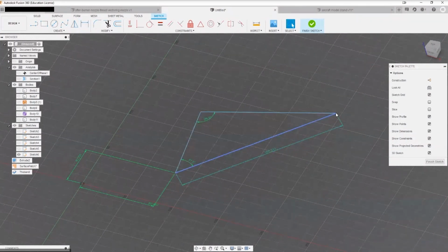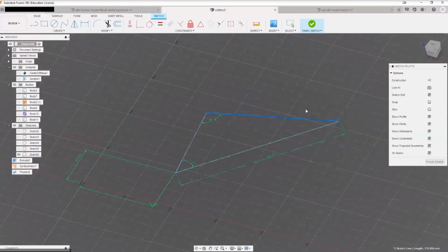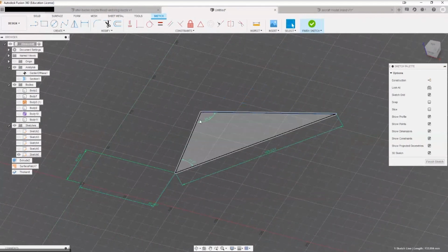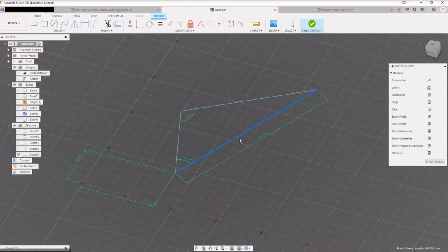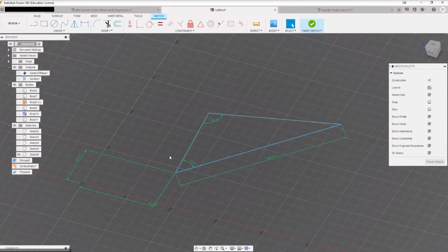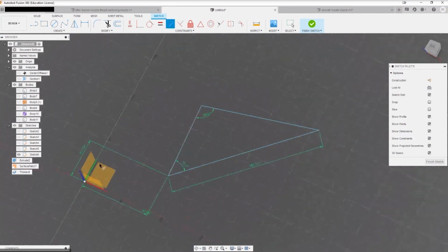Yeah. So let's see what happens now. Oh, suddenly this is rotating, right? So we've fixed the point, we've fixed the angles between them, fixed the distance, but you need to sort that out. Again, when you're designing something, you're going to have a specified set of requirements, so you'll already have all of these dimensions ready. We can switch on the origin, because apart from the origin, it also specifies the different axes. So if we want this to be parallel to that one, you can go here and say, okay, I want it to be parallel, right?